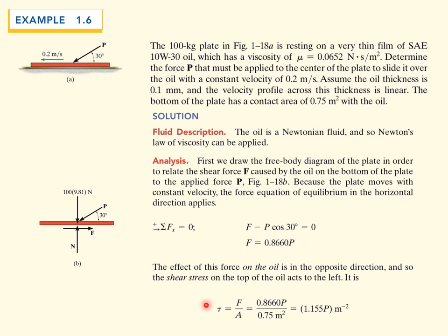We can calculate the stress on the plate. That's the force divided by the area. So here's our force divided by the area. We're told that at the bottom is 0.75. That's the contact area. So the stress is going to be 1.155 times P.